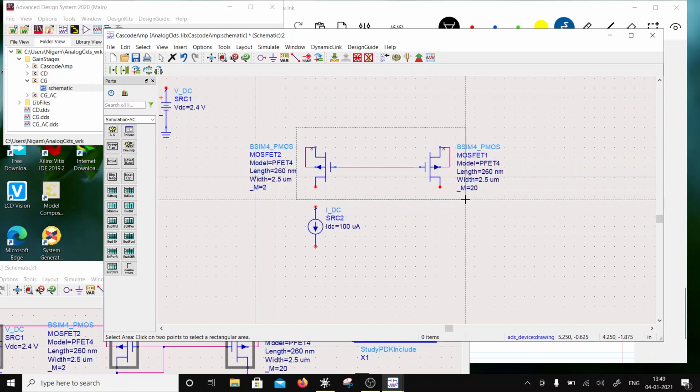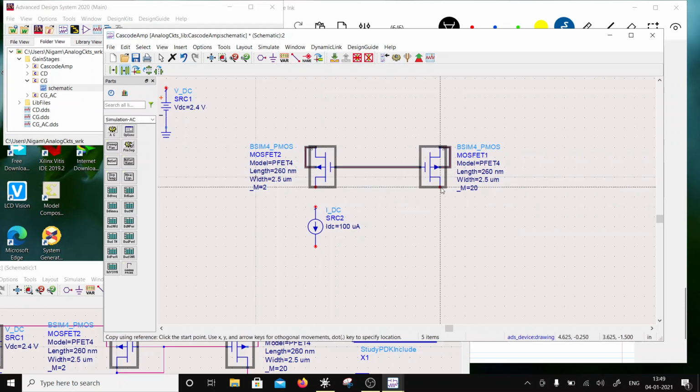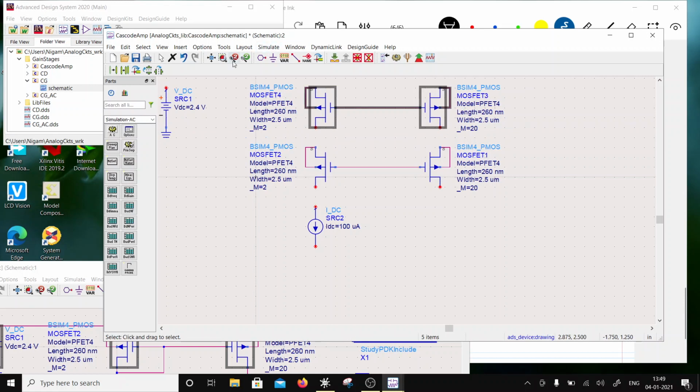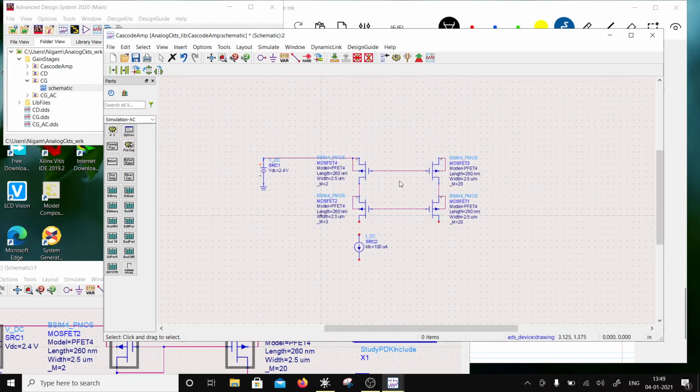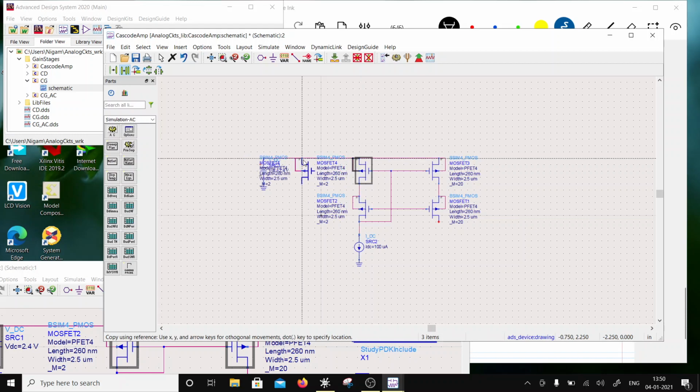Okay, so what I'm going to do is repeat this stage on the top, just like when I designed earlier in the previous session, right? So now I have this like this, and this is my supply voltage, and this would be connected over here, and here I will draw the current out. And next I want another transistor which is 1/4 the size, so I'll just copy this one over here, move the supply out a little.